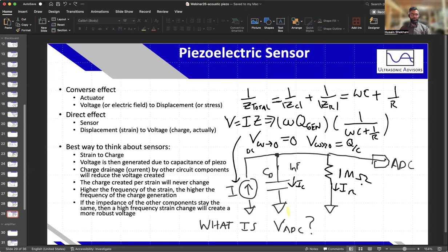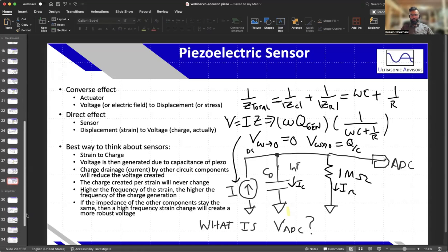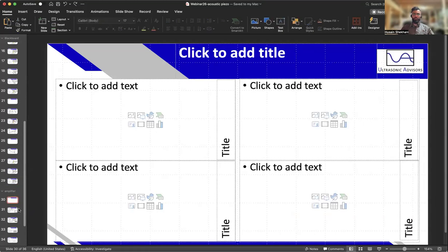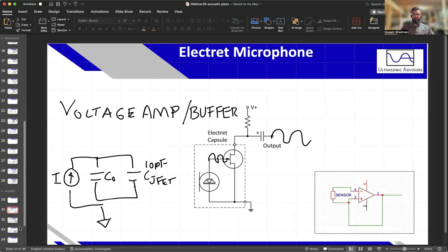very quickly drop off. If you've seen my previous videos, when I try to measure the voltage on a piezo element that I squeezed and try to measure the charge, it goes down very fast if you measure it even with a 10 megaohm. So you cannot use this circuit at all to measure DC. You can't use your oscilloscope to press a piezo crystal and measure the voltage. It's just going to deplete immediately, with the time constant of these two components. So it becomes very important to understand and to appropriately buffer or protect the voltage or charge that your piezo element is producing, because anything you attach to it is going to create a filter, and also reduce the voltage amplitude.